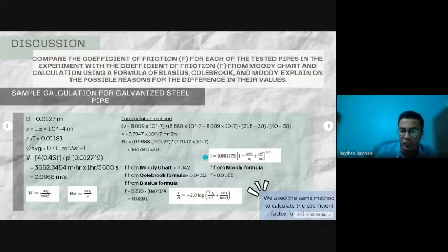the formula is 0.001375 times the quantity 1 plus 200 over 200 times the relative roughness over diameter plus 10 to the power of 6 over Reynolds number, all powered with 1 over 3, which gives the answer 0.0432.